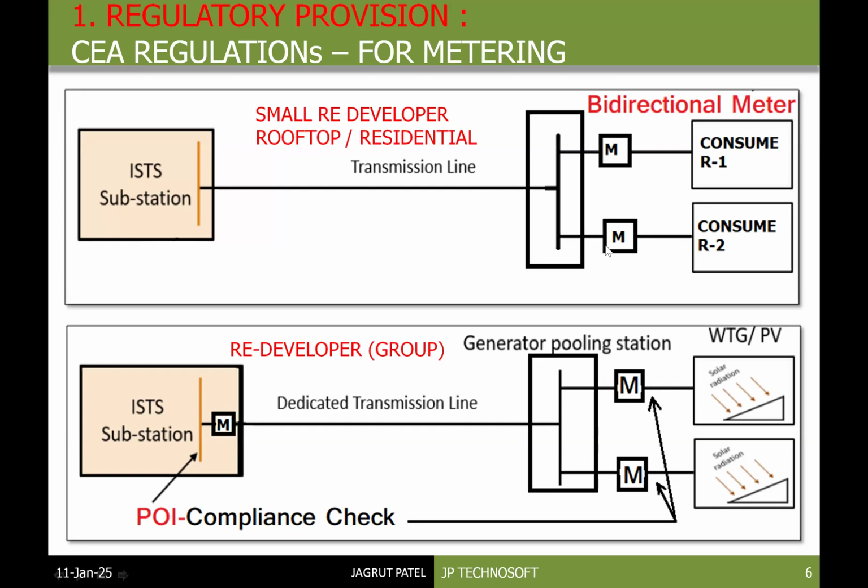These meters only meter kWh, because these are residential provisions. As per tariff regulations, the meters placed at consumers' premises only meter kWh. They do not have the facility to measure PQ parameters like power factor and other parameters. So whatever disturbances, whatever power quality issues arise because of implementing solar for residential consumers, will be handled by the DISCOM. This is the meaning of this.